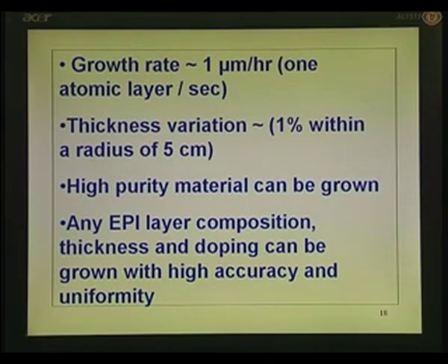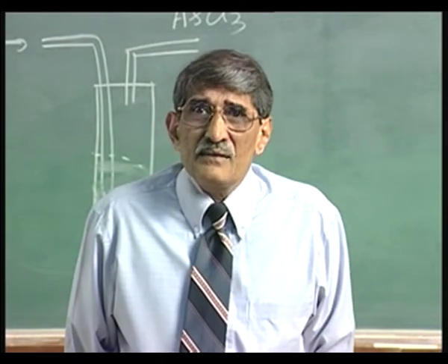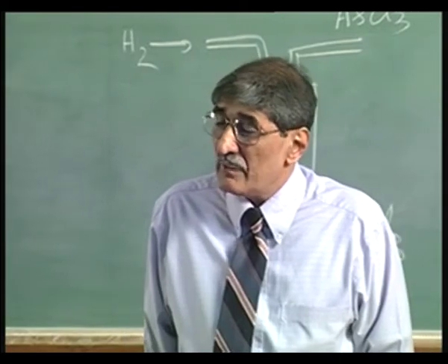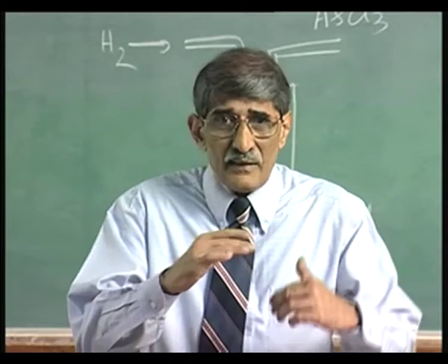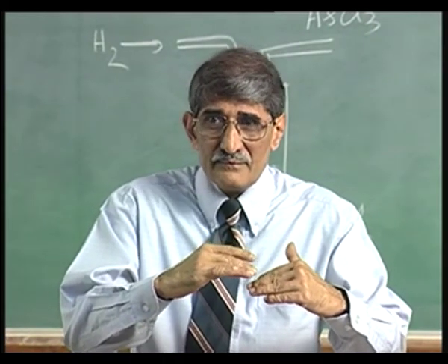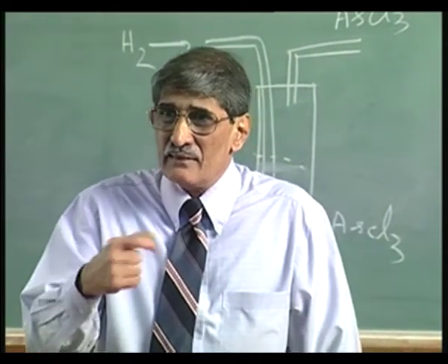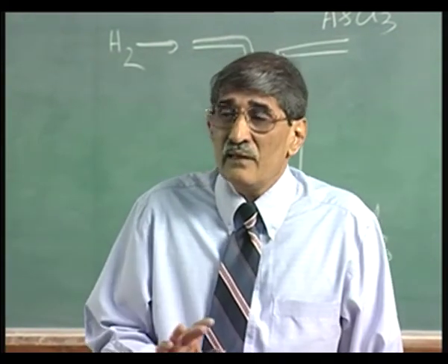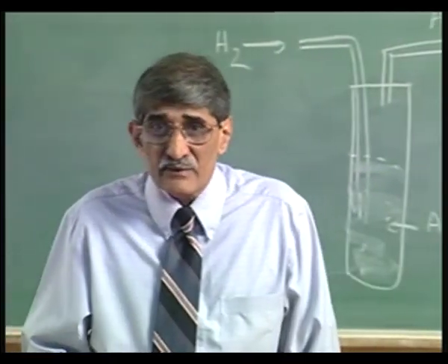Okay? Let me just sum up at this stage. The MBE system has gained a lot of popularity, and today people are accepting to use this for some commercial applications because of the high quality that you get. Particularly those who want very thin layers, for example, aluminum gallium arsenide, then gallium arsenide, a very thin layer, okay, at the angstrom level, then this type of approach is highly attractive. So, this is one of the most popular techniques which is used along with MOCVD.